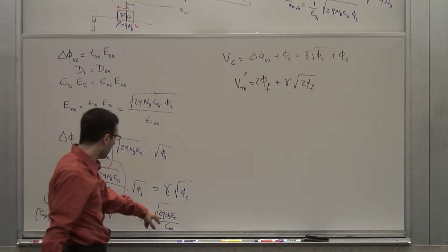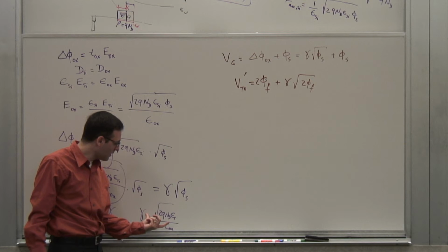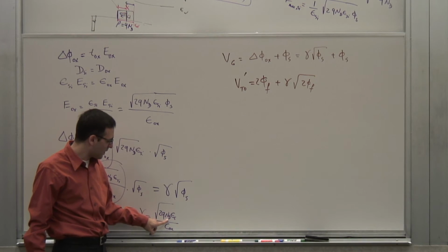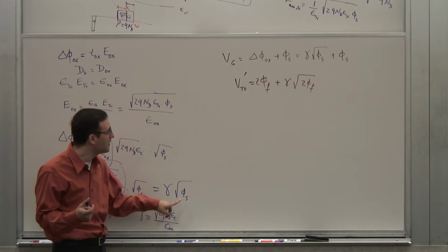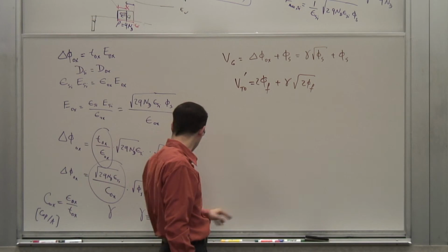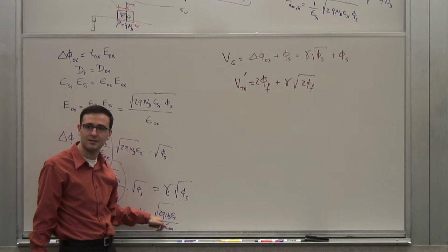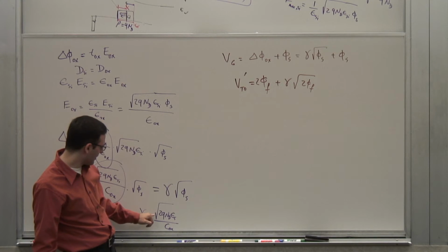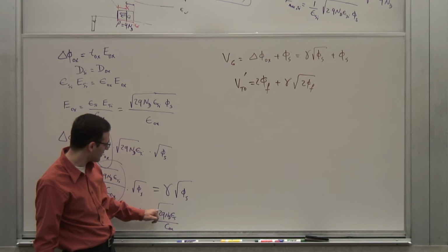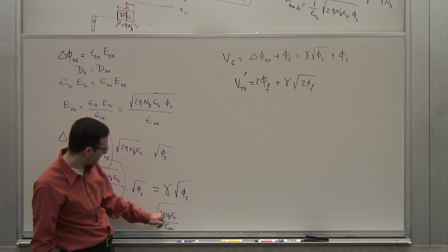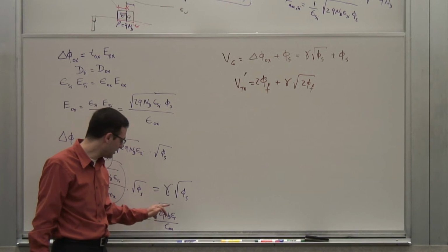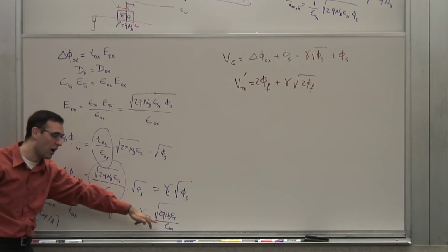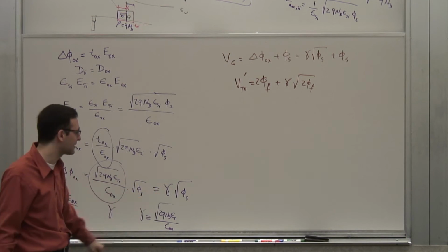Now, you see that many of the constants associated with the bulk of the semiconductor appear in gamma, right? And actually this looks very much like a depletion capacitance. So one-sided depletion capacitance, if you look at the expression. So effectively, gamma is not quite a unitless quantity, it has a square root of the bulk doping, but it's a quantity that's like a ratio of two capacitors. The depletion capacitance, which is the one that you see underneath, and the oxide capacitance, which you see on the top. And you'll see what the significance of that is later on.